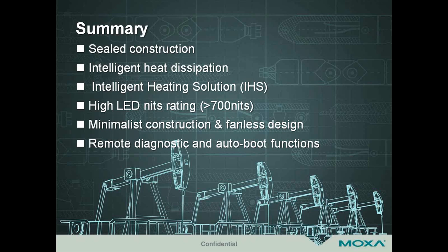And what was the second half of the question? The expected life of the HMI. Well, that would all depend on the manufacturer. I know that Moxa has stated warranty and lifelines to the products that they produce, but that would all depend on the embedded or self-standing system you're trying to place in the field. I can only speak for Moxa in this standpoint: we'll state a warranty and operating temperature, and it should be completely standard in your facility because your operating environment is under the max operating temperature that we test for.